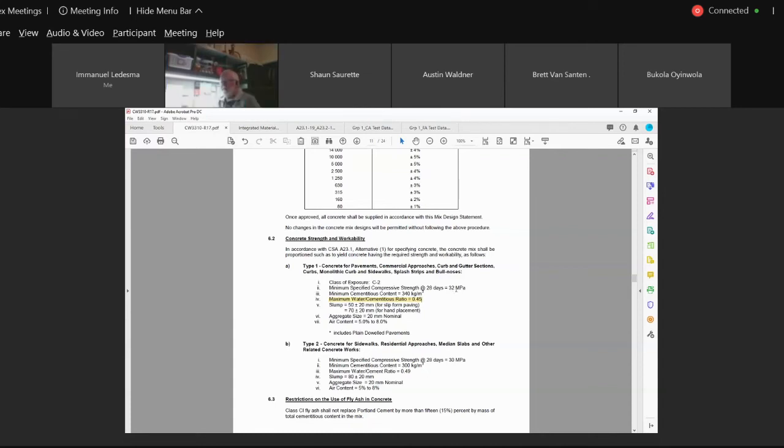You may have, like I say, maybe 40 MPa in here. So be it. It's based on the class of exposure. What's our concrete subjected to? Our pavements are subjected to freeze-thaw and chlorides. Remember, we use de-icing chemicals with our salt when we add it on the streets to get rid of ice. So our concrete is exposed to the attack of salts. And more so, the salt basically attacks the reinforcing, which expands because of corrosion and pops the concrete. Not so much salt attacking the concrete.